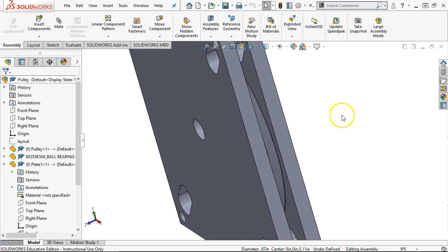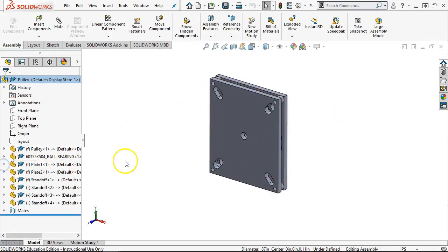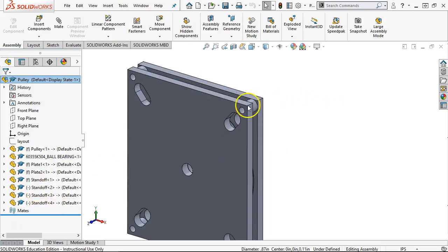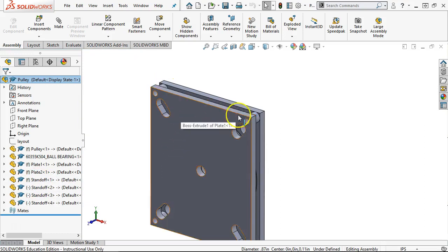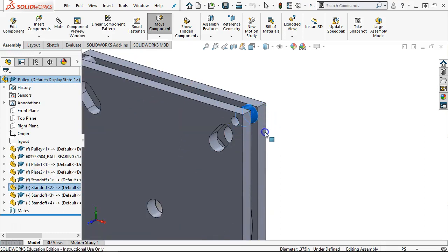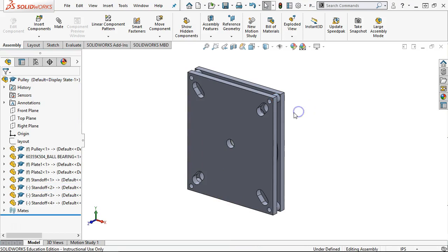All right, so to that end, I kind of discounted, and we did all of this as a top-down assembly. When you're looking at these arrows and the virtual components, the standoffs were still minus, and I'm not worried about those being underdefined, because the first standoff was drawn in context in its location, the others were brought in, and the only thing you can really do, and you can't see it for the most part, is spin. I'll worry about those or let those spin a little later.